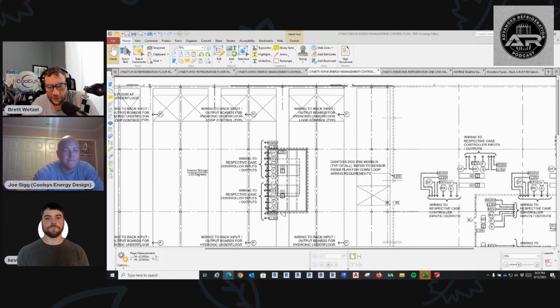Well, when I did a store up in upstate New York, even for regular HFC or HFO refrigerants, they had to have a shutoff via the leak detector that would signal to the BMS or EMS to shut down the circuit. They would shut down the EPR, shut down the liquid line solenoid, with the hopes that it would stop leaking. Sure, you're isolating the coil basically, right?